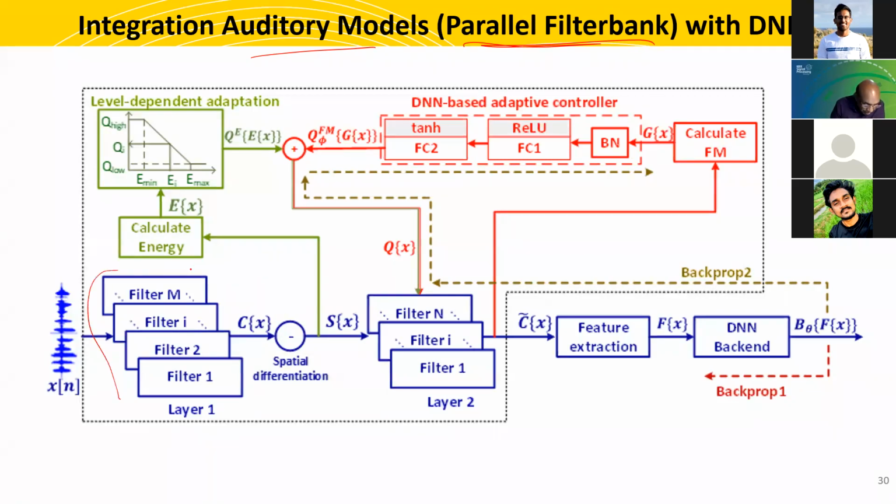So we have parallel filter banks here. Instead of adapting this filter, we decided to leave that. There's enough evidence in the cochlea that a second filter is available, which is the tectorial membrane filter. So we have second filters here, and we will change the characteristics of these filters. We will keep this fixed and change these ones. But these are all FIR filters, so that you can actually use all machine learning algorithms. In previous versions, all of them were IIR filters.